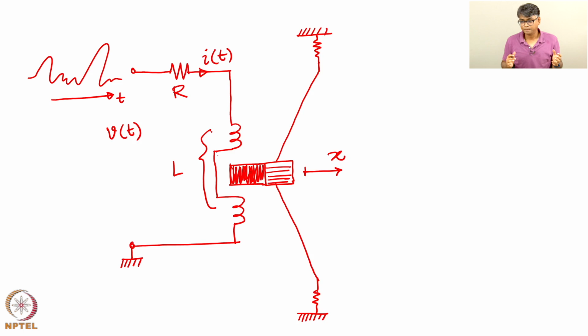If you have seen such speakers in your local neighborhood functions, those big speakers, sometimes their covers are open and you can see this diaphragm beating like a heartbeat. So that beat is what is caused by the movement of this bobbin. The movement of the diaphragm is the one that causes the sound waves and the music that we hear.